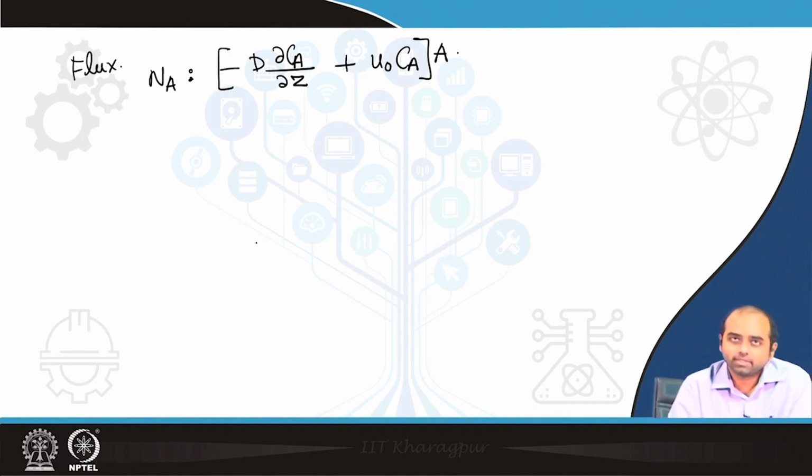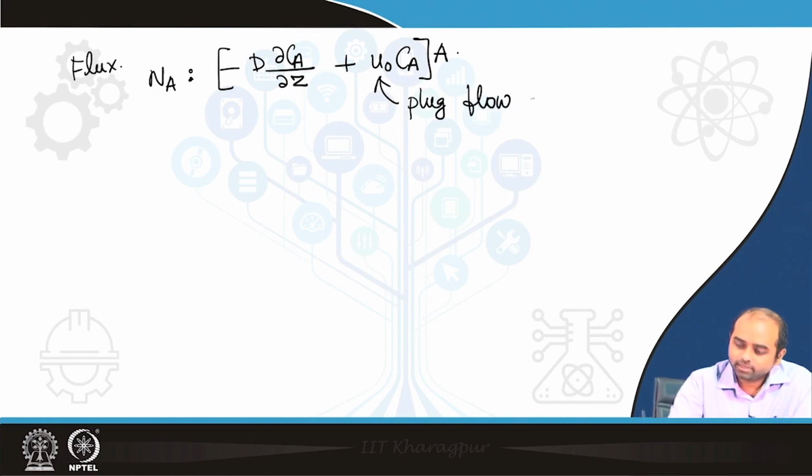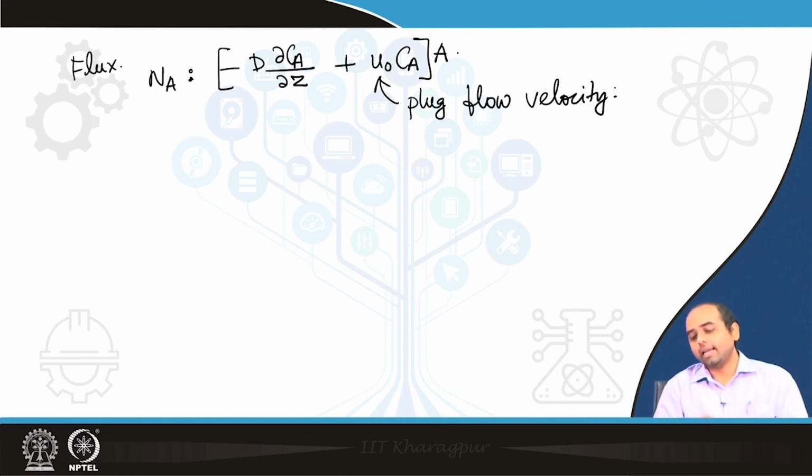Right, I just multiply with the area here. So, u0 is the plug flow velocity, right. The other option is to calculate this based on the pressure distribution, either following Ergun equations or Darcy's law. That is something you can also work out, or you can also use the Darcy-Brinkman equation to estimate precisely how the flow variation or the hydrodynamics inside the packed bed happens, right.